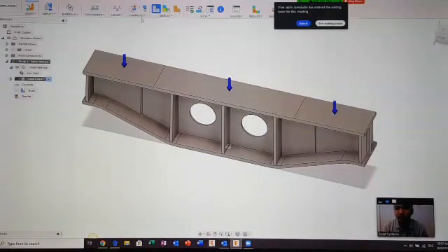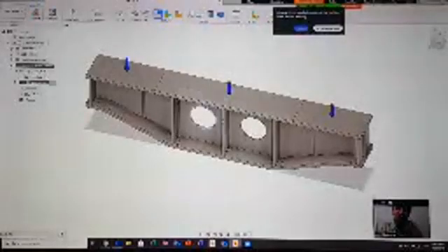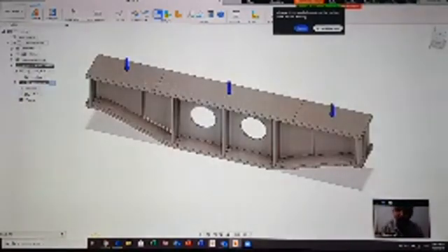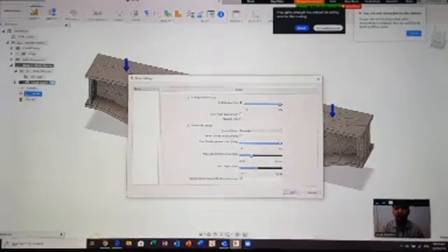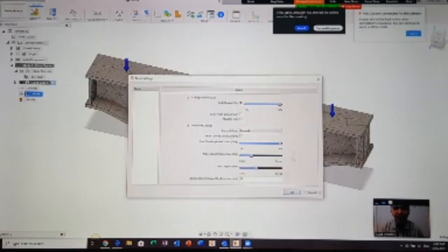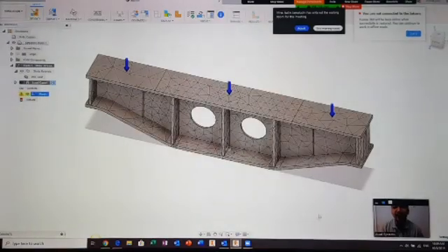Then here, if you see the contact here, contact means you want your assembly to undergo the simulation also. Then you can use the contact. But mine's one. Your element order, you can change between parabolic or linear. Let's say for linear, basically we have the structural shape with the same geometry, so we can use the linear one. But for the parabolic, you can see your shape will become a solid element. Alright, so let's say I'm just going to leave it as the default without changing anything inside here. I'm just hitting OK.